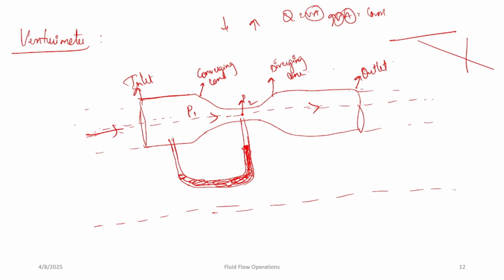a straight length of pipe of at least 5 to 10 diameters, to reduce any turbulence inside the pipeline. Commonly the diameter of the throat is kept around 0.5 of the inlet diameter, or one third to three-fourths of the pipe diameter.